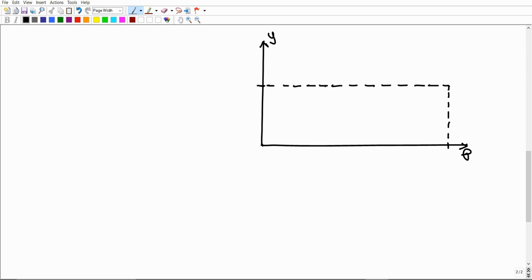You have to represent all the rise, the dwell, the return, and the other dwell, the 4 periods of the cam or the follower displacement, as already described on the description up there for the given problem. It should be represented within this dash line. But you have to break it down into 4 periods. We have 4 periods, right?